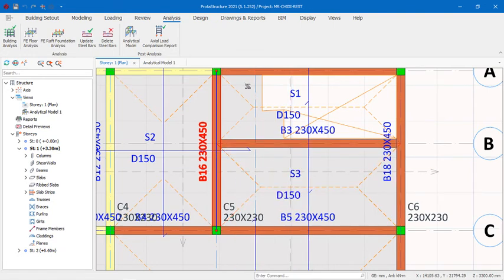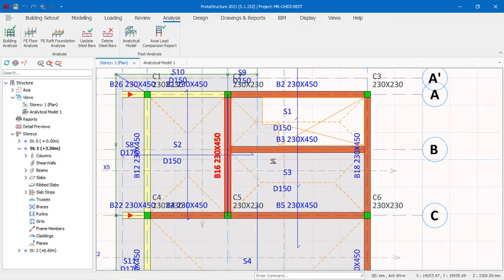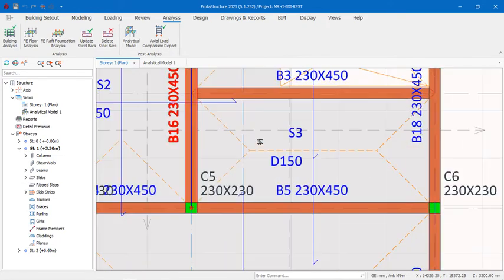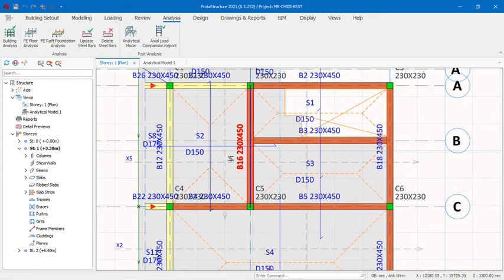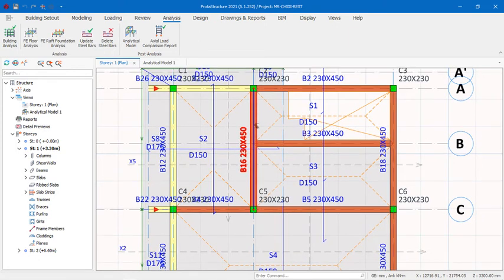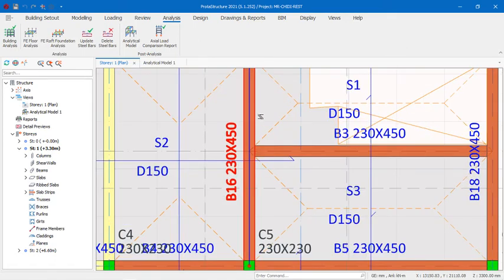So he started noticing cracks on some of the beams. Then he called me, so we had to pick those things part by part manually. Of course, we were not the designer, somebody else designed. So when we started noticing these cracks, we had to run this manually. We discovered that the beams supporting all those point load columns acting on them and spanning up to three, four, five floors fail in shear.